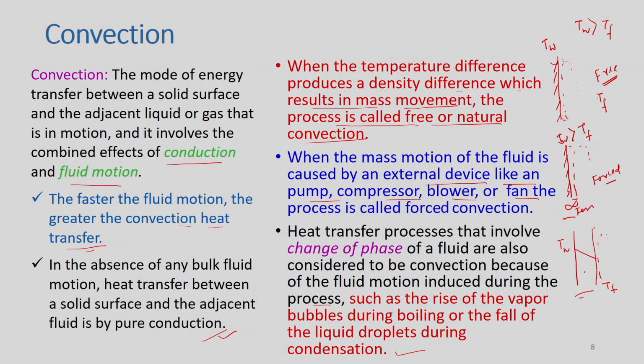So, what I have drawn here is the wall, and in the immediate vicinity of this wall there will be a fluid layer. This is the fluid layer. Before convective heat transfer takes place, there is a very thin layer that exists when the temperature of the wall is more than Tf. So, here pure conduction will take place, and then only convective heat transfer will exist.